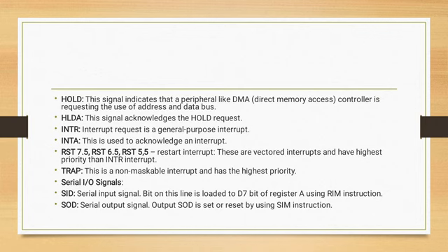Next, the HLDA. This acknowledges the hold request. It is the signal for hold acknowledgement. That means it indicates the hold request has been received. After removal of the hold signal or the hold request, the HLDA goes low.